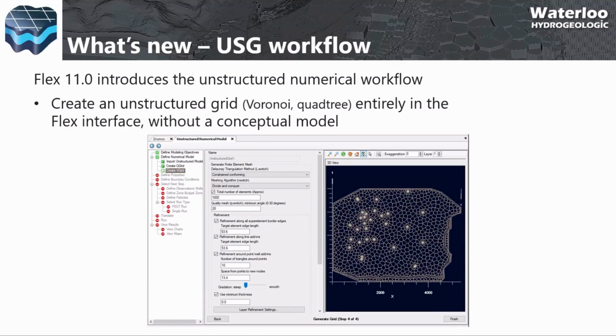Flex 11 also introduces the unstructured numerical modeling workflow. In previous versions of Flex, unstructured grids were always created in the conceptual modeling workflow. With this release, you can create an unstructured grid at the start of the modeling process and assign model elements onto that grid, like with the numerical modeling workflow for structured grids.